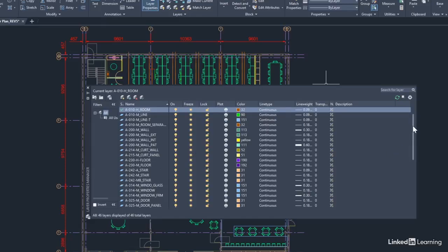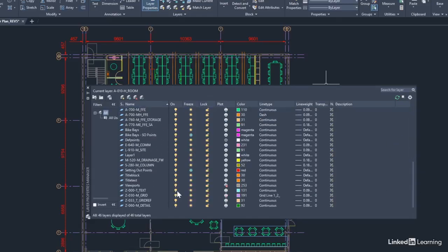So I can slide down here using the slider bar, and I might select, say, the grid layer. There you go, using color 191, grid line 12, line type, etc., etc. Now, that's all well and good with existing layers, but what happens if I need to create a new layer? Well, this is where these little icons here kick in. They're very useful. This one here with the little star on it is new layer. So you can see there I've got layer 2.